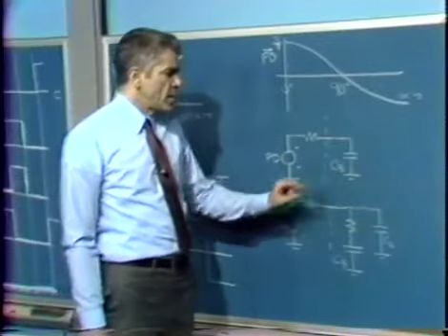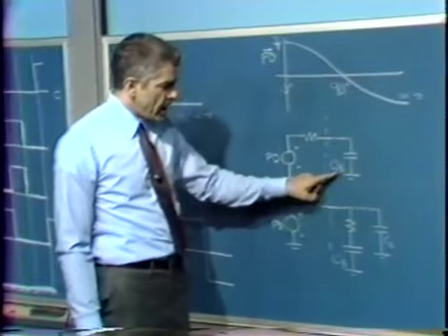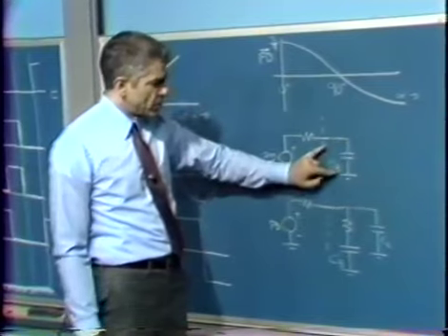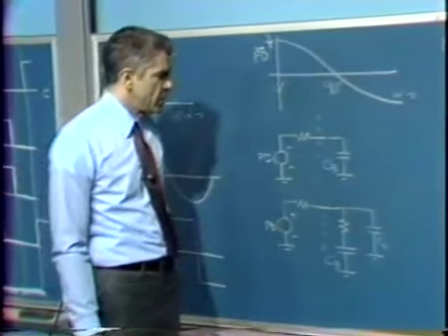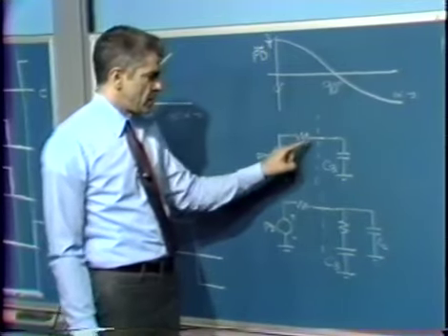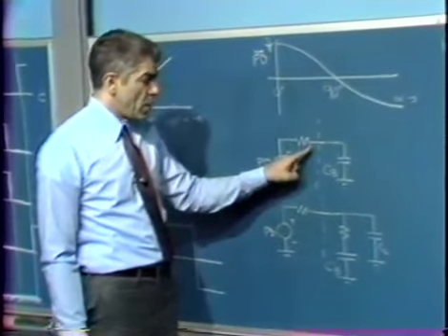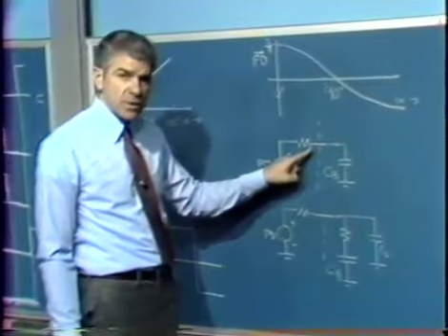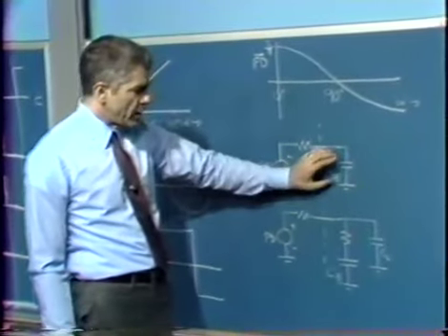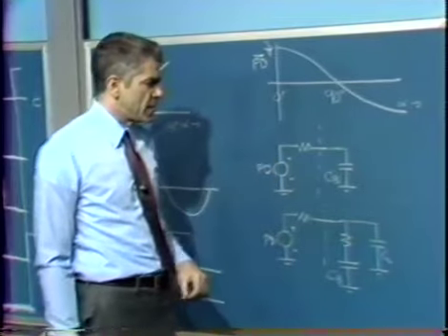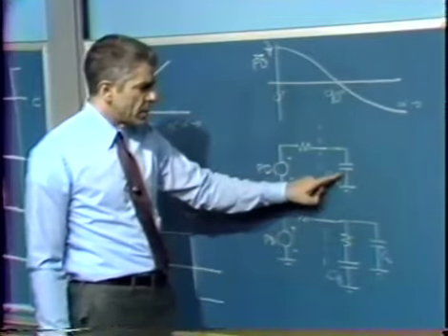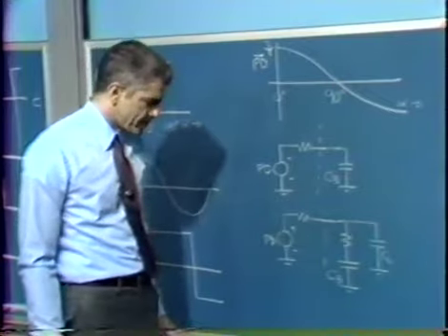Well, one thing we might do is simply add a capacitor, which I've chosen to call C big, across this pair of terminals, and that provides the filtering function. The signal here is really the raw signal from the phase detector before filtering, and we indicated we have to do some filtering. We don't want to apply a time-varying signal to the phase detector, so we might do that by simply putting a capacitor onto that terminal.